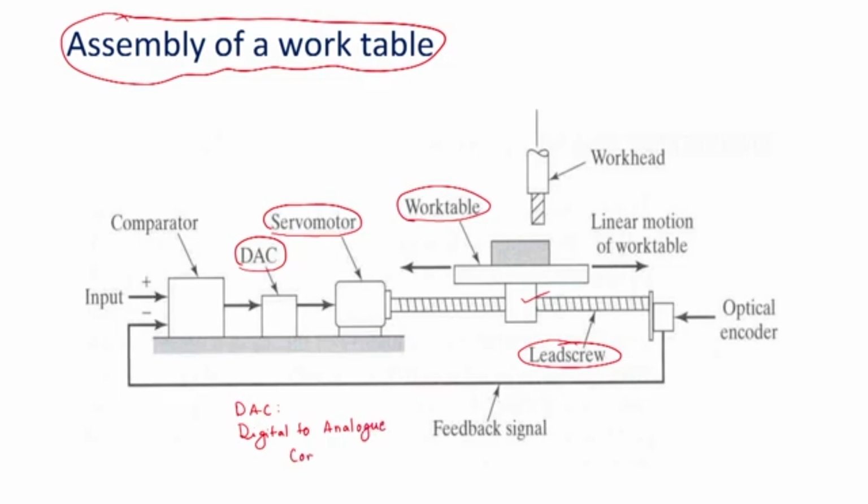Yes, so there is a need to have the optical encoder, the feedback system through which the process is being continuously monitored. Typically in CNC machine tools we are using ball, nut and lead screw. It is not the Acme threads, we are not using the typical screw and nut arrangement.